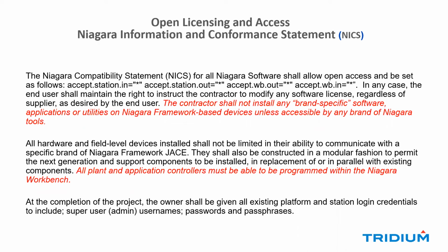Now, today, many manufacturers make their software available within the Niagara framework as modules so that you can use your standard Niagara tools to program VAV boxes and equipment controllers. There are others that, while they're not built into Niagara, can connect into the JACE and tunnel through the JACE and program the controllers. So the specifier, the owner, has to make sure they know what tools they're going to have available.